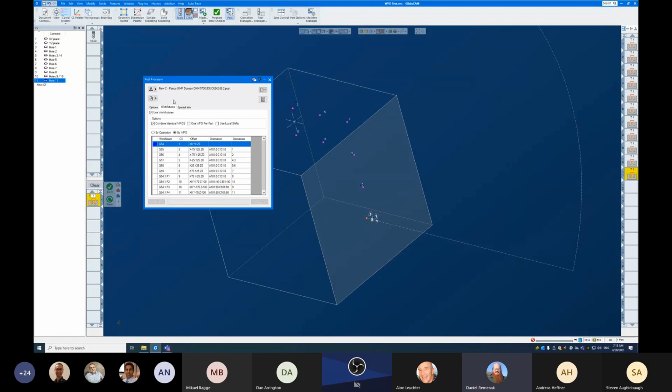It also avoids some of these more serious problems. In this case, I'm just using solution control to trigger some of these problems. But if you had a 6-axis machine, repositioning the 6th axis on a 6-axis mill will introduce some of these same problems, where you'll have the same CS and even choose the same solution for the 4th and 5th axis, but the points in that coordinate system are not going to line up with the work fixture offset that was allocated in a previous operation at a different 6th axis angle.